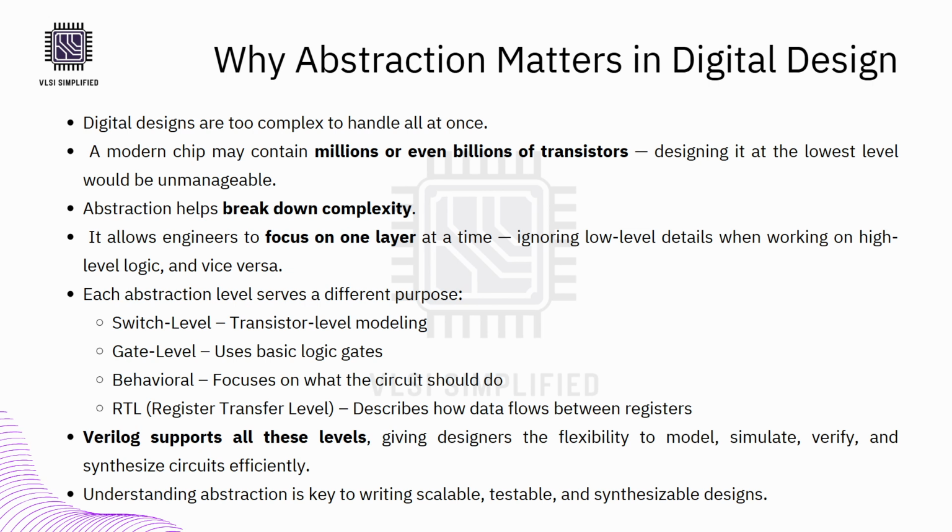So at the switch level, you will describe actual transistors. At the gate level, you define how logic gates connect. At the behavioral level, you will describe how the system should behave in response to inputs. And at the RTL, you focus on how data moves between registers under a clock. Each of these levels serves a unique purpose, and together they form the foundation for efficient digital design.